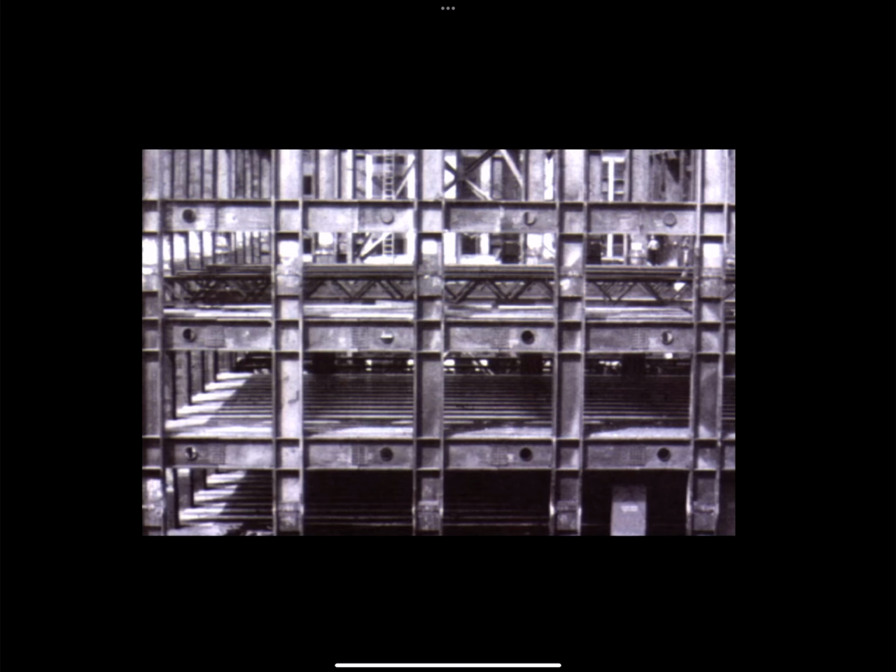So as the loads come down the building, the steel structure has to thicken in the same way that we saw with the Monadnock brick walls getting thicker, only now this all happens within the steel structure and it is not visible in the finished building. So these are custom fabricated steel components welded together from steel plate. They are not standard hot rolled sections.